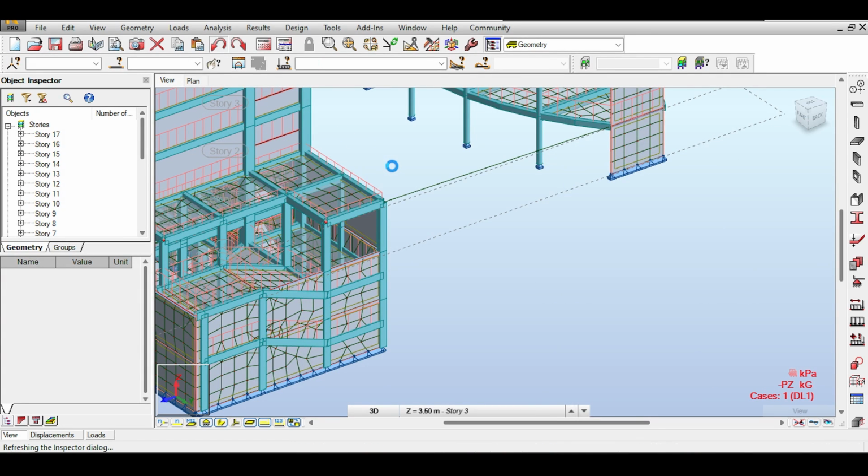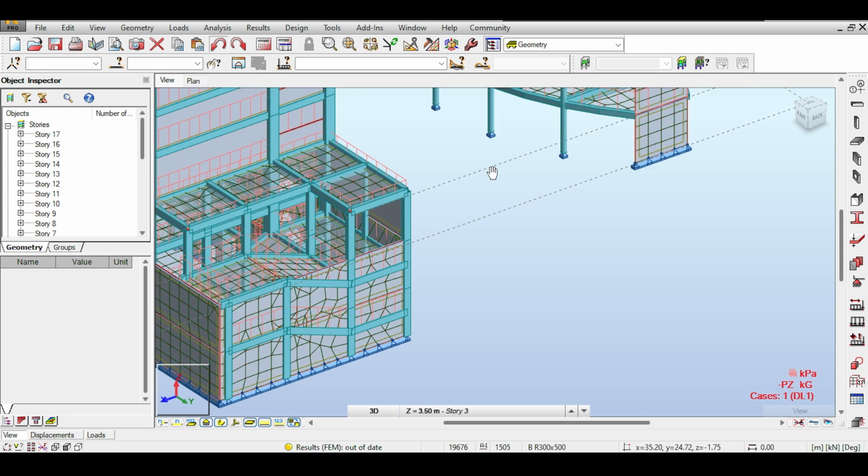So yeah, I think we have applied our wind load. At least I've showed you the taste of it. Now there are two topics remaining here. Of course, I need to fix my model. That's something I will do off screen. You know the error, there is overlapping panels, and that's something I can just easily delete the panel and redraw it. But the error of member without properties, that was a sneaky error. I think I've explained it to you and you know what happened.